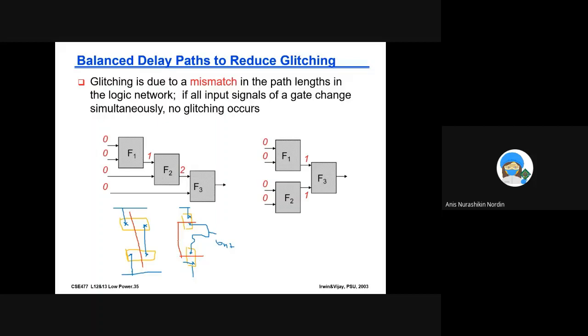delay, right? Polysilicon has very high resistance, and the signal, which is nice like this, will become muted like this, because there is a high resistance. So as you can see here, if you have these kinds of gates, it will make the signal slower. Instead of arriving on time, it will arrive late and very weak. So what we need to do is put in a buffer or optimize this circuit.